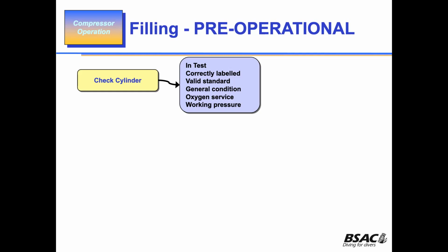And that's a club compressor as well. Somebody brings in a cylinder, says, fill that for me. And you check it and say, it's not in date. It hasn't got valid standards. I'm not going to do it. It's risky to you to even think about doing it. And if it looks tatty, it could be tatty. And if it's going to be for oxygen service and you can't do oxygen clean air fills, don't fill it. Decline to fill if in doubt. Exactly what I just said.